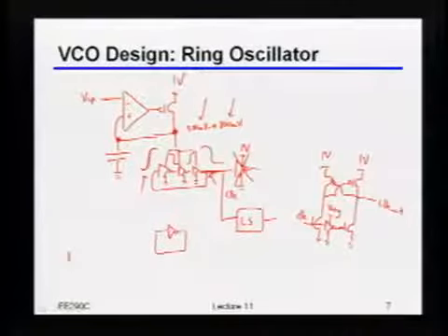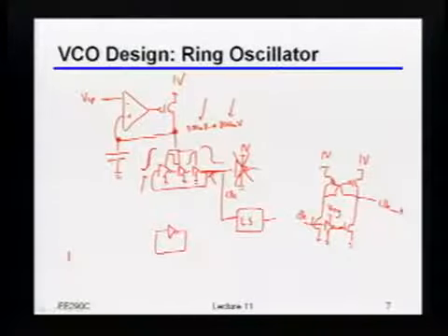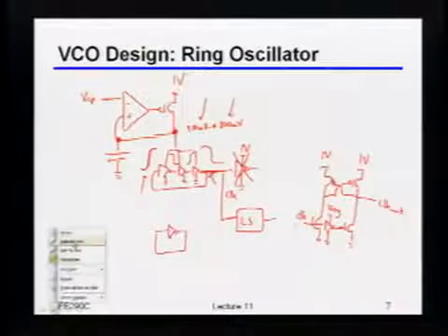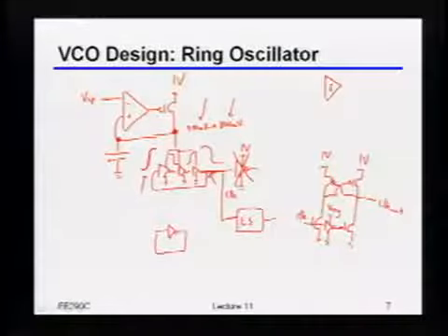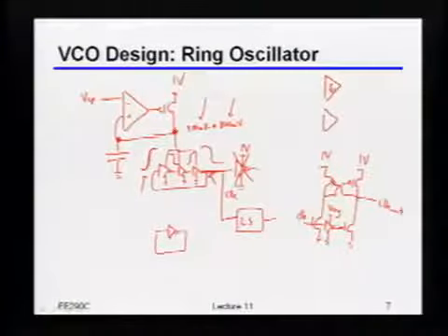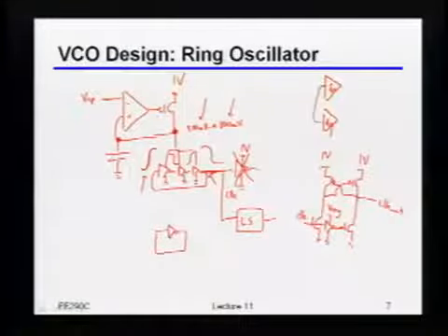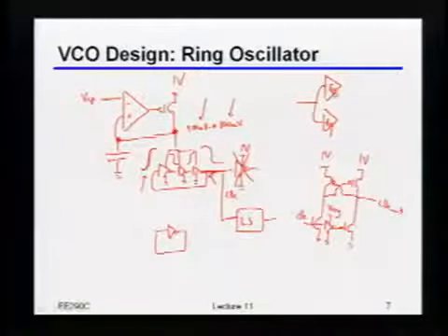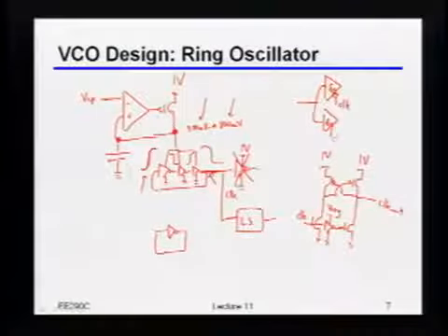Remember, I'm using this clock for a high-speed link. Just as an example, we talked a while ago about it, and we'll talk about it more very soon. A pretty typical way for me to do clock recovery is to 2x oversample.